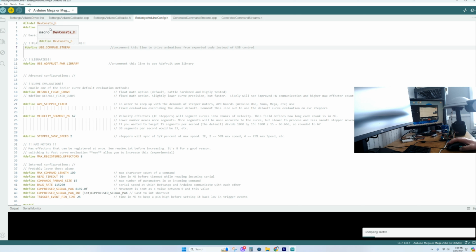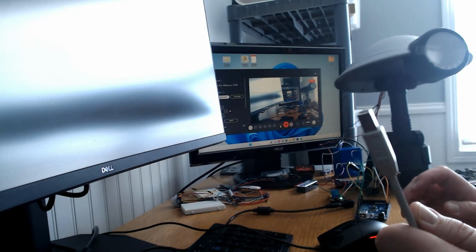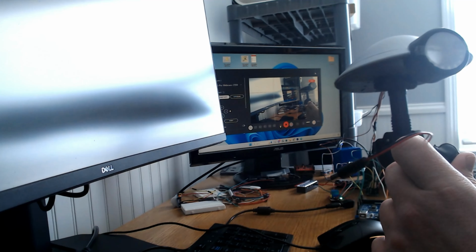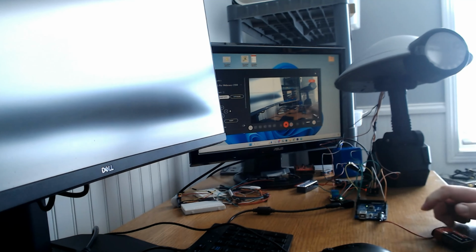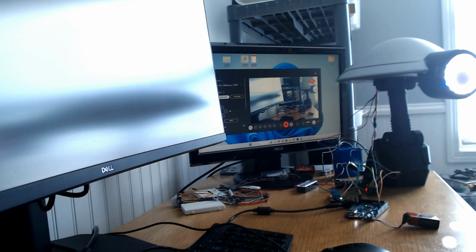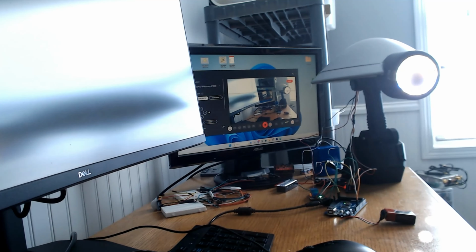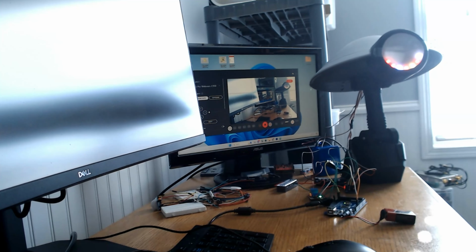It's uploading sketch. Alright. It's done and now it has started, and I'm going to unplug it and put a 9-volt battery in to power it up so that it's separate from the computer. Now I've completely unplugged it from the computer, and we're going to use a 9-volt battery to power the Arduino. And here you'll see the 12-second thing here. Now it'll stop for a 5-second delay, or whatever delay you decide to put in there, and it'll start back up, and it'll be on a loop.